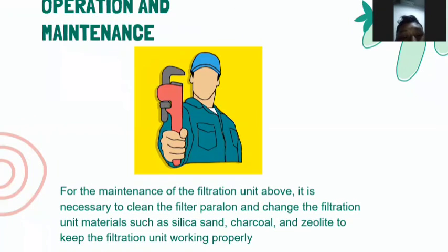Operation and maintenance. For the maintenance of the filtration unit above, it is necessary to clean the filtration unit and change the filtration unit materials such as silica sand, charcoal, and zeolite to keep the filtration unit working properly.